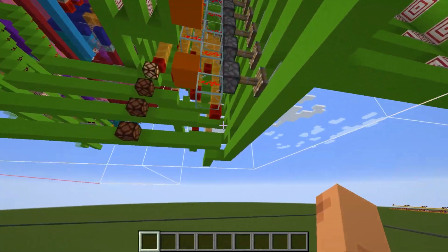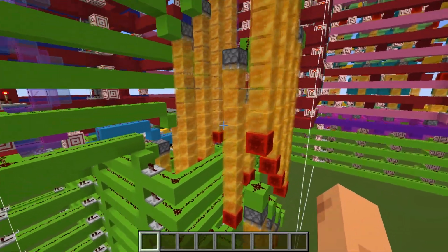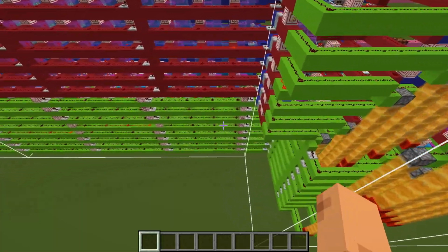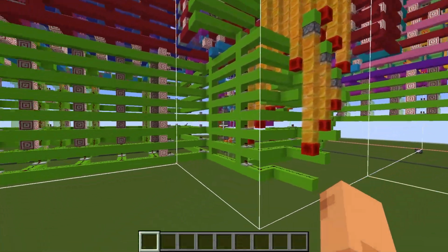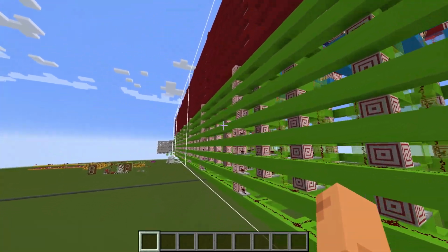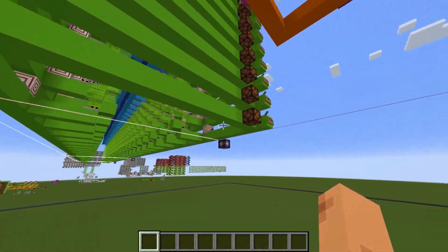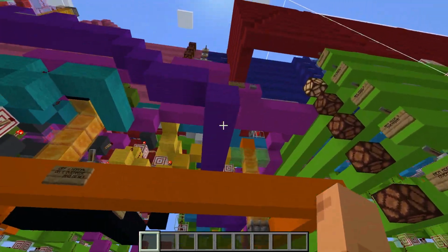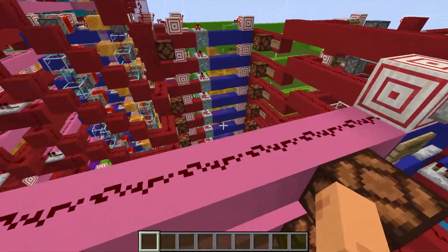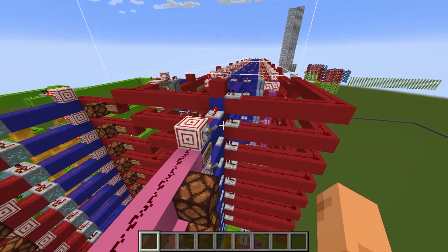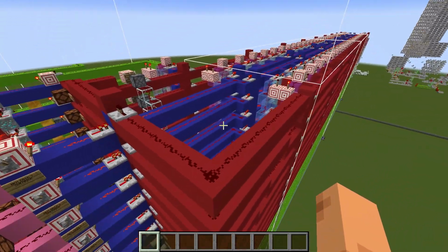So what that allows us to do is basically hardwire the setup of our control unit so that we know that we're going to be reading from this side the odd bytes, or whatever it is, for the opcode, and this side for the data. So it allows us to simplify some things about how we decode instructions, because we can get essentially both values at the same time.